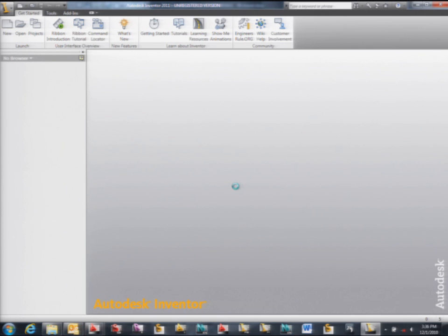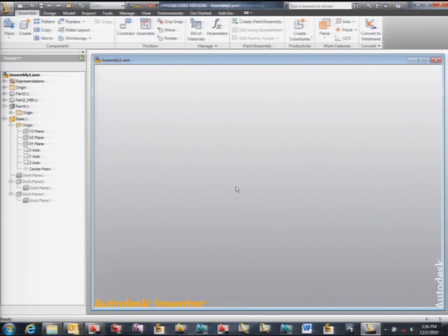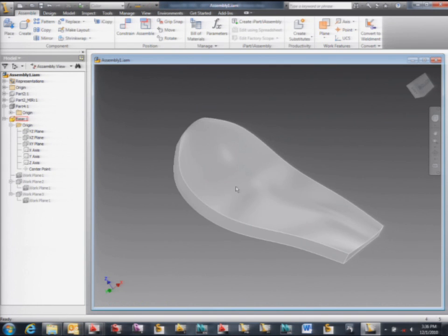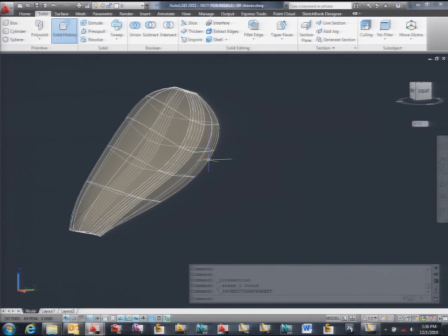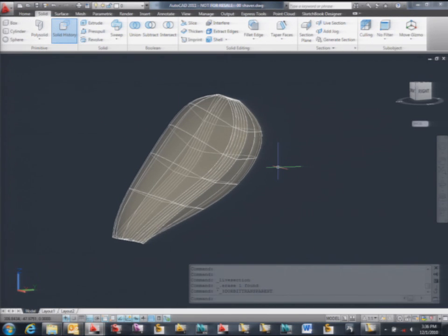And in AutoCAD, I previously divided the solid, the whole surface, into two solids. So going back to AutoCAD for a second, before making the solid, I created a network surface in the middle of this because I knew that one part was going to be the plastic part, which was the bottom and the two sides and the patches with the surface on top of that. And the other part would be the cover, which would be some kind of transparent plastic. So I wanted to take those two parts already separate into Inventor. And that's what I did, but it doesn't make sense to do it now, it's just creating a network surface here in the middle.